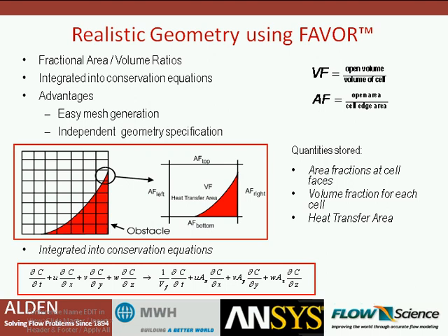What we're showing here in this example is an image of the imported geometry. As you can see here, we block out those cell faces and those cell volumes, and ultimately don't allow flow into certain parts of the domain. The nice part of this is not only does it make the meshing real easy, but we don't have the momentum losses typically seen in a stair-stepped grid.